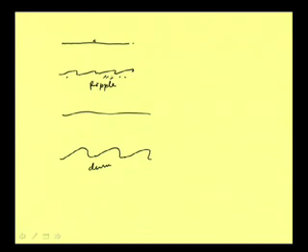Of course, many find it very difficult to distinguish between these, while these sizes can go up to say 0.3 to 0.4 meter at maximum, it can go 0.4 or 0.5 meter in smaller size, but in bigger rivers it can go to a larger dimension also. And because the flow is moving here, the difference is that when it forms a dune, the flow coming here moves like this and there is a separation of flow, which means there will be some deformation, and this will induce some amount of energy loss in this part.